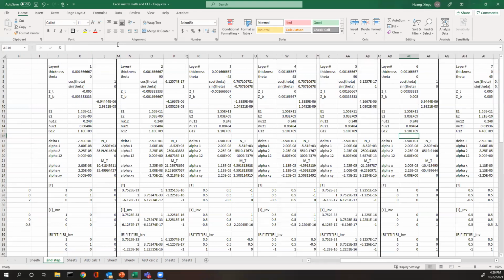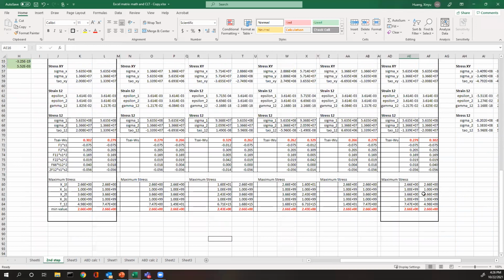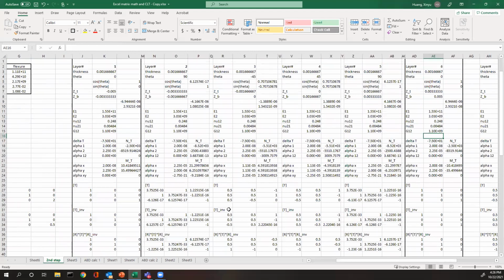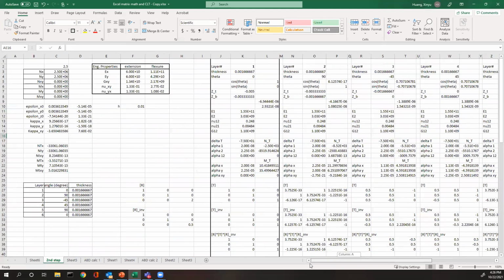Okay. So what it does, effectively, when you do this, in my case, my code recalculates everything automatically. It immediately redistributes the load. Load distribution is different now. Then I can go see my failure criteria. Okay. Now remember, I didn't dial the load down. The load has remained the same. This is biaxial tension, right?